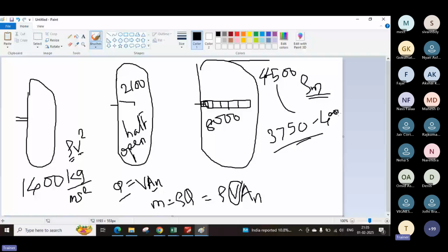You can use this to size the diameter of this nozzle, like how to size or what is the deciding factor for this: the rho v square values. So these are the typical rho v square values we consider to size the nozzle sizes of a vessel. Now this is typically for the inlet and the outlet of a gas nozzle.